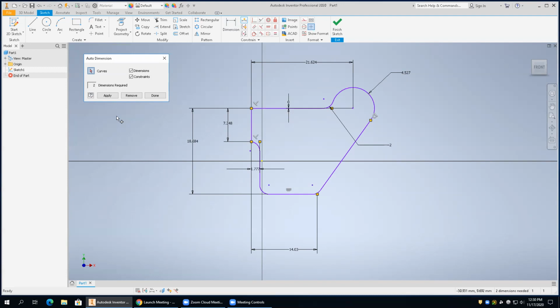If you really wanted that locked down to a specific point, you could do that. So for instance, if we constrained the center of the circle, we could come up here to that little lock and select the center of that circle. I've locked that. If I look at my constraints now, I have 0 required. I'm now fully constrained because it can't move left, it can't move right, and it can't move top to bottom. Okay? Everybody get the idea?